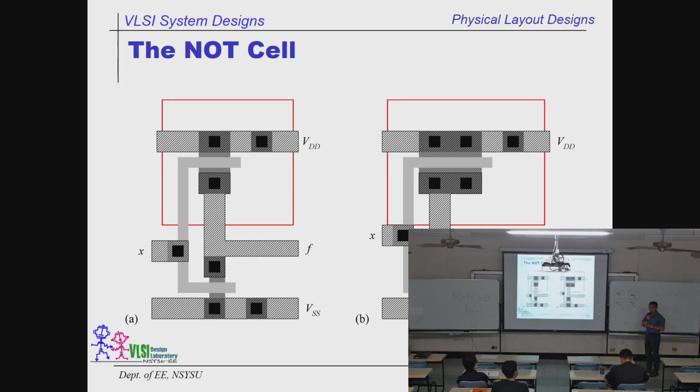Okay? Remember the homework assignment I asked you to do the first week? 2-to-1 ratio? That is why. Because we want to equalize the current given by the P transistor and drained by the N transistor, because the mobility of the electrons is at least double that of the holes. So this is a better version of the inverter, relative to the previous two. All right, is that clear?